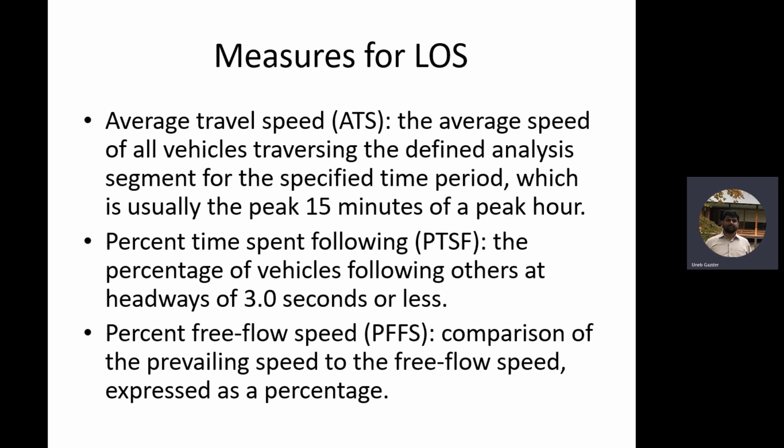If the other car stops, how many seconds do you have to stop? 3 seconds. 3 seconds is nothing, right? You put your foot on the brake, 3 seconds are gone. So this is considered very, very short. If your headway is 3 seconds or less, this means you are following the other driver. The amount of time in which your headway was less than 3 seconds is the percent time spent following. So you drive for 10 minutes. Out of 10 minutes, there was 1 minute in which the headway between you and the other car was 3 seconds or less. So 1 out of 10, 10%. Percent time spent following is 10%.